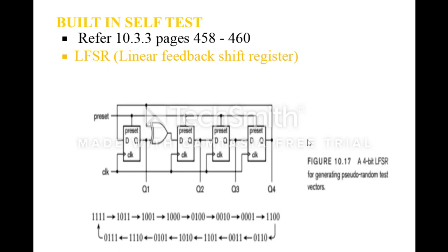This figure shows a 4-bit linear feedback shift register that generates a pseudo-random test sequence. It is taken with 4 flip-flops.